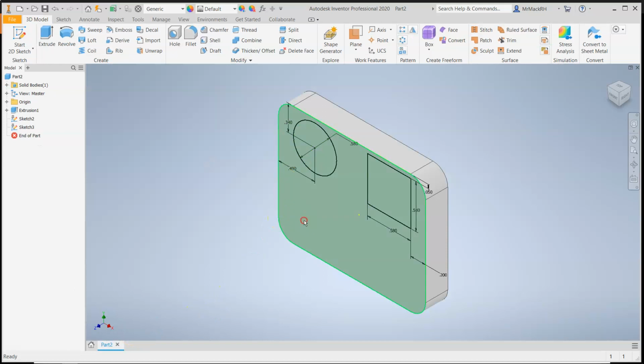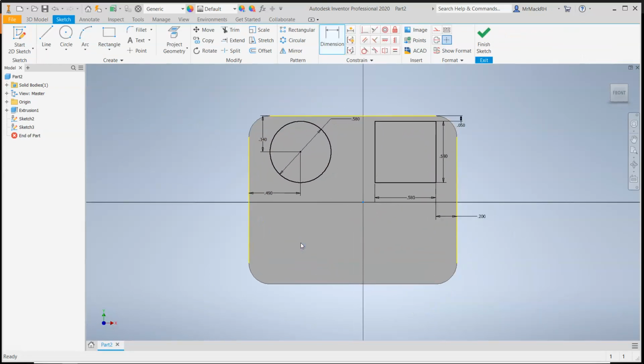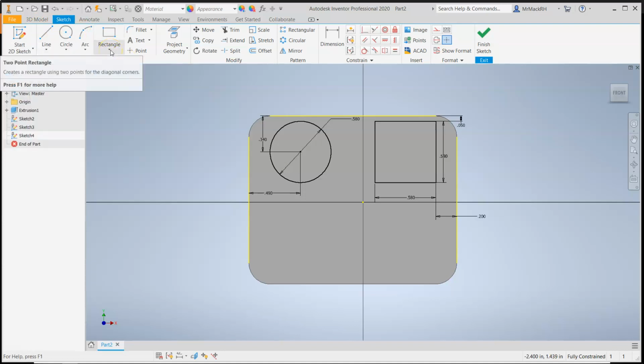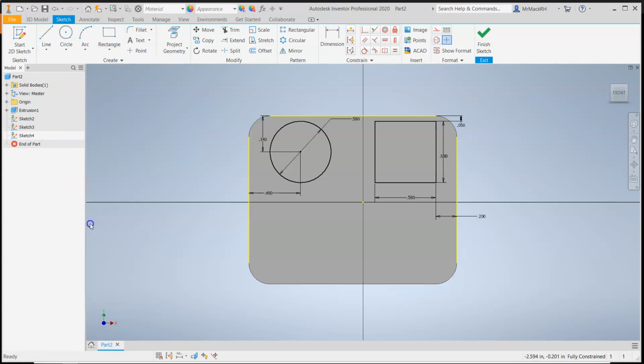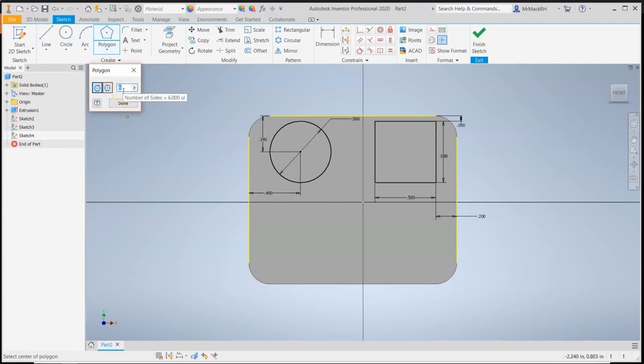So we're back here. Right-click, New Sketch. And now, how to draw a triangle. We have circle and we have rectangle. Triangles are polygons, just like rectangles. And so we drop down the menu here, this little arrow, and we go all the way down to polygon. And then for sides, we type in 3. Done. Now when I click on the Polygon tool with 3 sides, click in the center and then move my mouse outward, it creates a triangle.